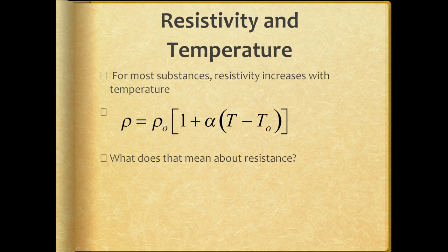And since that standard resistivity constant is calibrated for 20 degrees Celsius, 20 degrees Celsius is automatically what goes in here for the standard operating baseline temperature. Everything else you plug into the formula is just there to offset it from that baseline temperature to better represent its electrical properties at its present temperature.